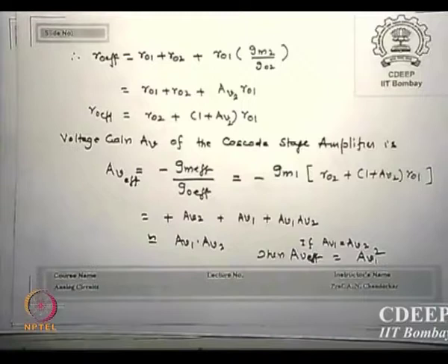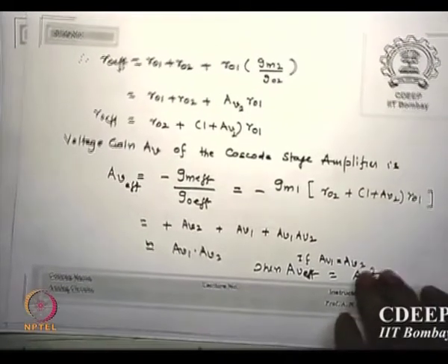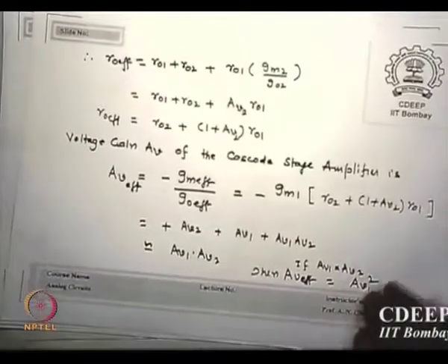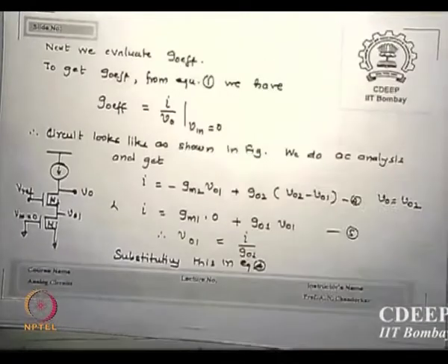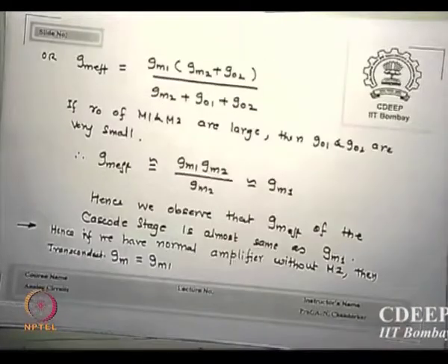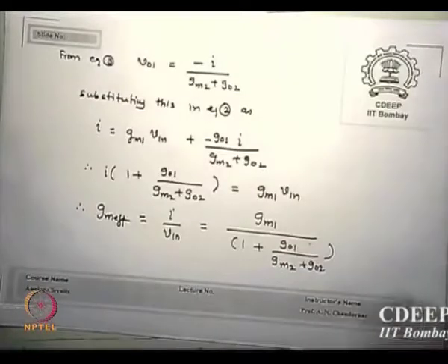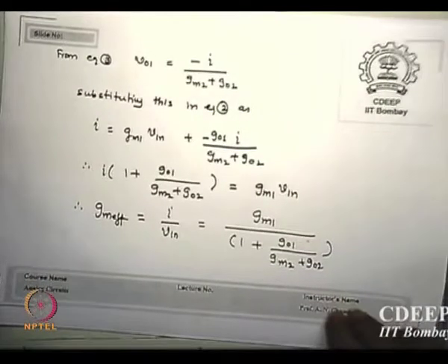So what is the advantage of cascode? Cascode is a very interesting device that allows you to boost output resistance without changing the transconductance, and that's something no one else can achieve. This is normally not done so much in discrete amplifiers. This is always done in integrated circuits because it is much easier to adjust GM1, GM2, identical ROs, everything is possible on a single chip.